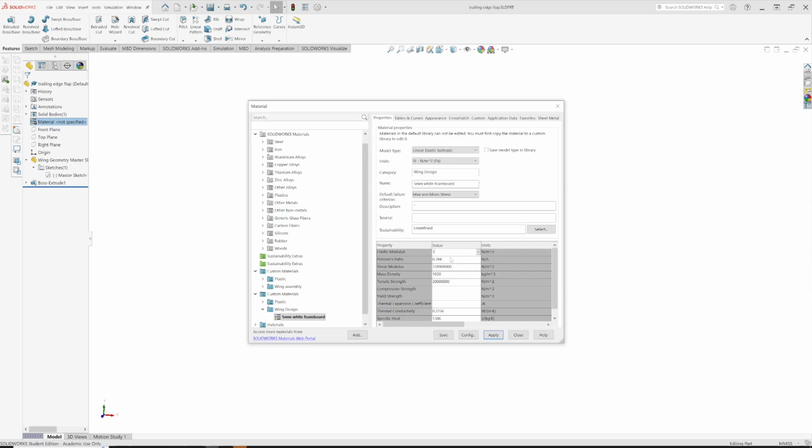So I can type that in, 1.8, using the notation E, so does it mean exponent, 1.8 times 10 to the 8, and then it puts all the zeros back in for me. Poisson's ratio has to do with the way when you stretch something, how it pulls in the other direction. We'll just leave that. It's around 1/3 for most materials, so we'll just leave that as it is. It doesn't make a huge amount of difference for us.